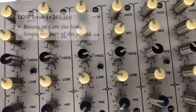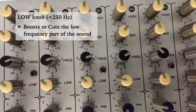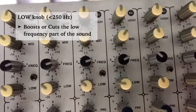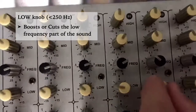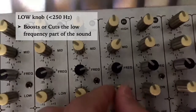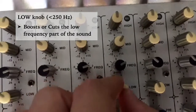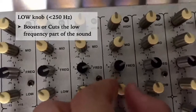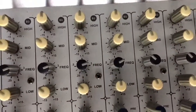The low frequency is for you to boost or cut your sound wave in the low frequency range, which is probably anything below 250 Hertz, maybe 100 Hertz or below. These are all the low frequency. So let's do an example. Okay, now I'm going to boost the low. Now you can hear my voice is very, very low. And then I can reduce the low as well. Now it's a bit sharper. Okay, so you can play around with this in order to get the best sound effect in your hall.